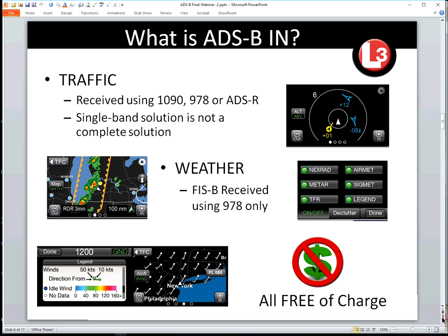What I mean by that is sometimes people say, hey, I've got an ADS-B compliant solution. I have a 1090 transponder, and they're out in a remote area. Let's say he's in a Cessna Citation making an approach to landing in a remote Idaho airstrip, and there's a Cessna 150 out there, and he's got a 978 UAT solution. So he thinks he's met the mandate. They're both right. They've met the mandate. But the problem is when that 150 turns base and he just thinks he has all the traffic information out there, we need to realize 1090 is a different frequency than 978. Those two devices don't speak the same language.